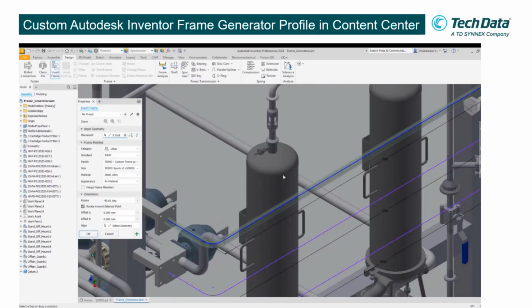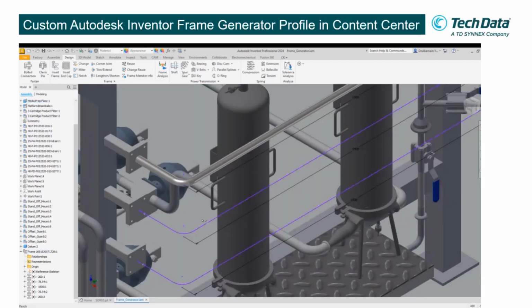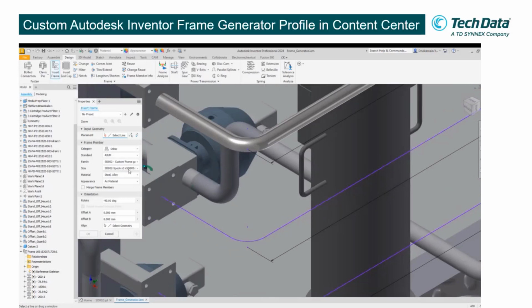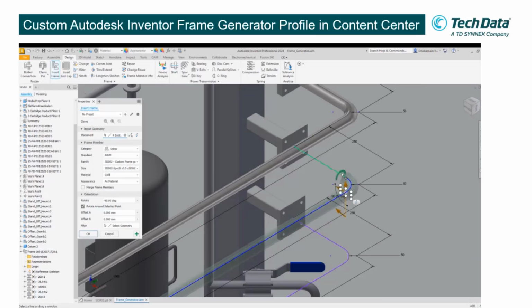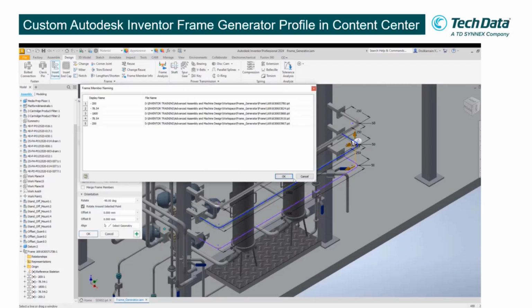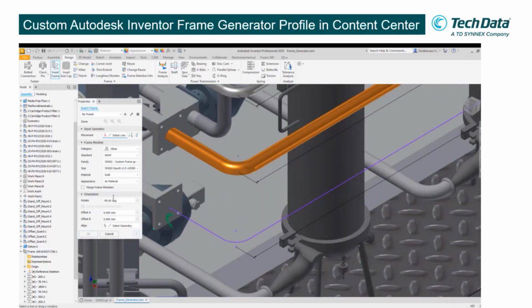And then we can apply. We can rename the steel structure file differently if you want to. And this is spec A. Now let me repeat again to create a new one with spec B. It remembers the previous selections, so let me select for the second one, and then apply and create new frame. You can see the second one is gold in color, because for spec number 2 I purposely put the material as gold just to show the differences.